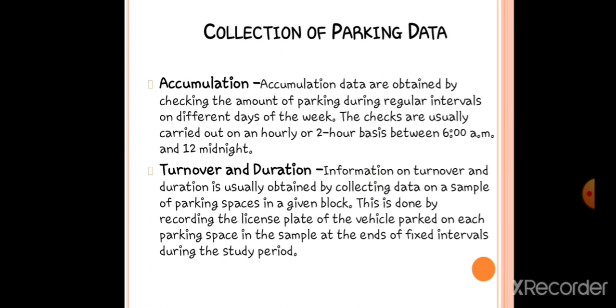Collection of parking data. Accumulation. Accumulation data are obtained by checking the amount of parking during regular intervals of different days of the week. The checks are usually carried out on an hourly or 2-hour basis between 6 a.m. and 12 midnight.